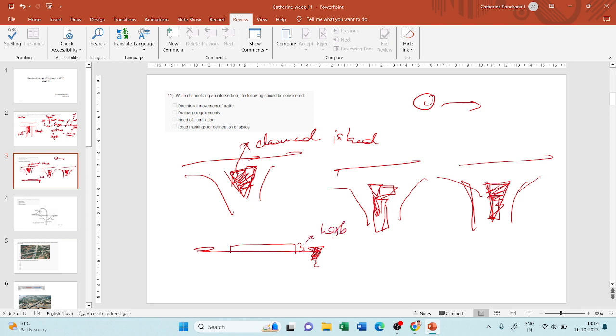Okay, most of the times it will have a curb, and this curb should be provided on all important roads and important intersections on 2-lane roads. Okay, so it should have a curb, that is it should be raised when compared to the level of the road if the roads are important.